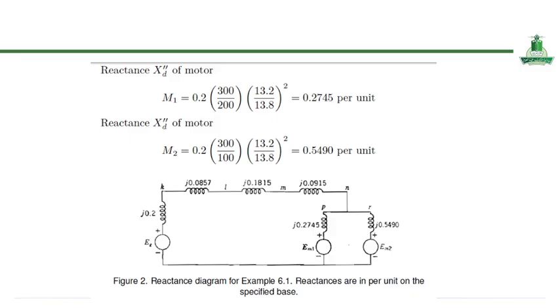And the unifying per unit reactance diagram is extremely useful, as you definitely know, because it allows the entire power system to be analyzed using a single consistent framework, regardless of differing voltage levels or equipment ratings and so on. So it forms the basis for calculating fault currents, voltage drops, and system stability under transient conditions.